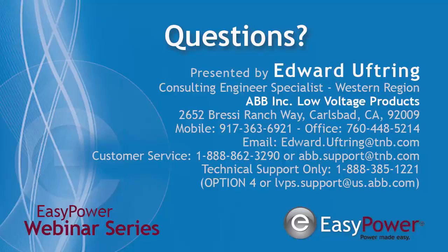In the utilities at the power production side, the breakers are controlled by different relays using two CTs. Why are breakers not built containing controls within themselves? It's a space concern, actually. Our breakers actually have the CTs in them. We have a reduction side with our new Emax 2 breakers where you can put the control up there, but typically you don't want the controls coming from the breakers because of the stress of a full load being turned on at the breaker.